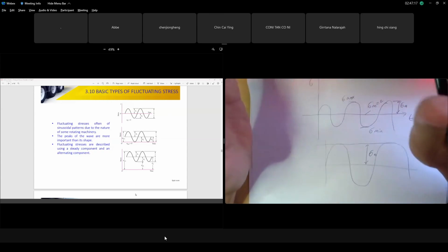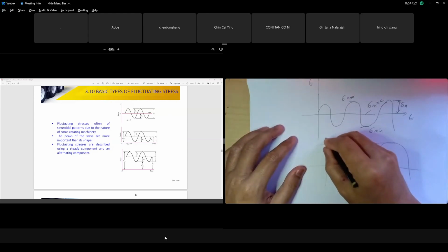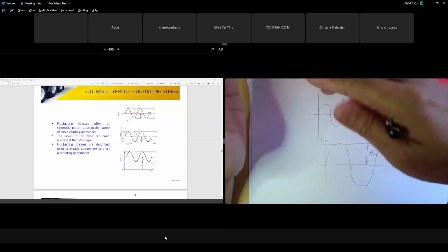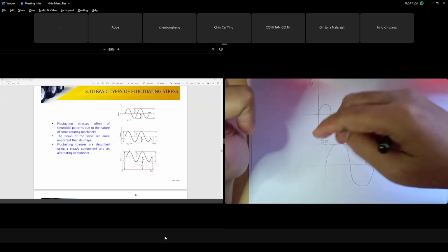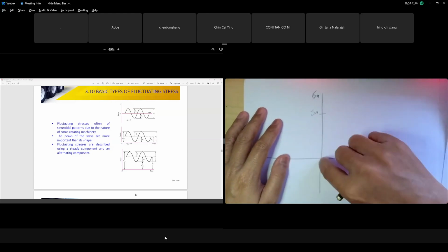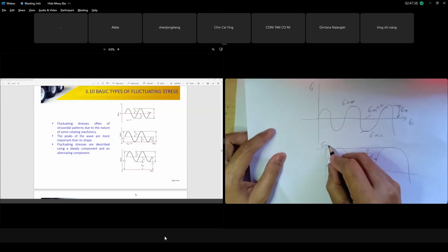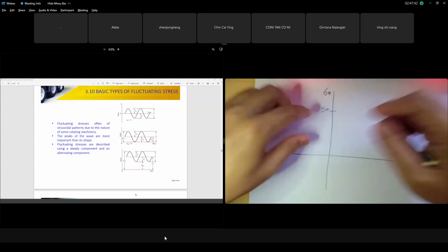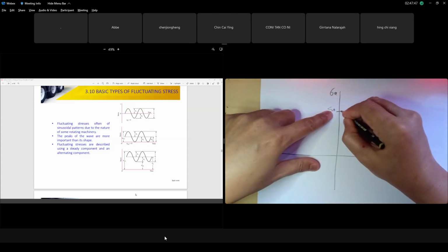No, SUT. Sorry guys, I twisted it. SUT should go on your axis. Our limit is SN. Remember, SN is fatigue loading because of your stress, your amplitude. Amplitude means you have maximum and minimum, but we go for complete reverse. All the points here are where the mean is zero. Mean is zero, so your limit is SN, because it is fluctuating, the endurance limit is our strength. Endurance limit. Earlier I said SUT, I got dizzy. Okay, SN, the limit is SN.